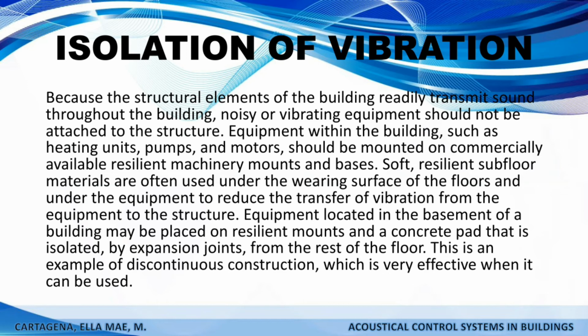Because the structural elements of the building readily transmit sounds throughout the building, noisy or vibrating equipment should not be attached to the structure. Equipment within the building such as heating units, pumps, and motors should be mounted on commercially available resilient machinery mounts and bays. Soft resilient subfloor materials are often used under the wearing surface of the floor and under the equipment to reduce the transfer of vibration from the equipment to the structure.